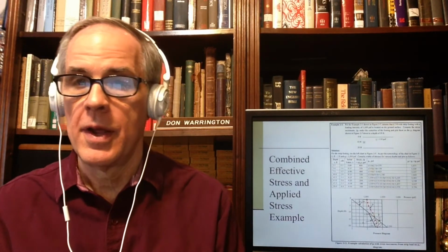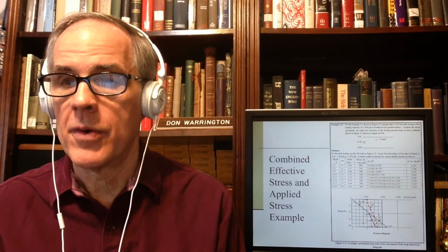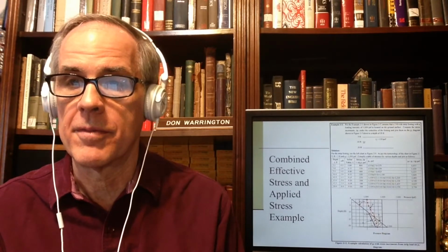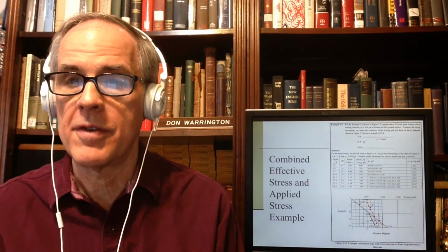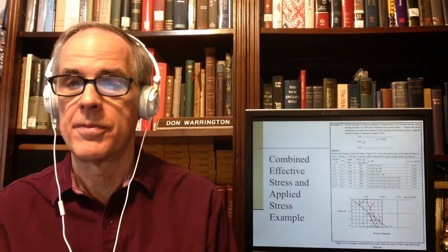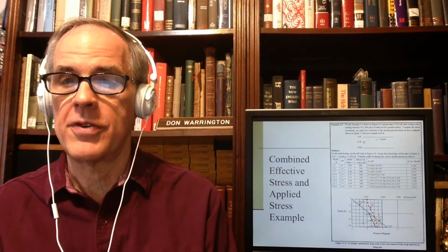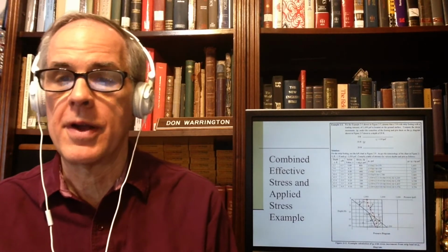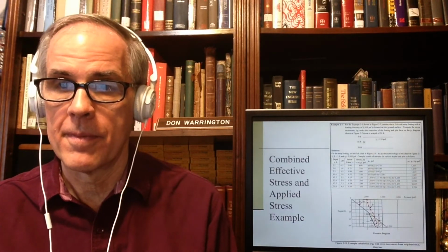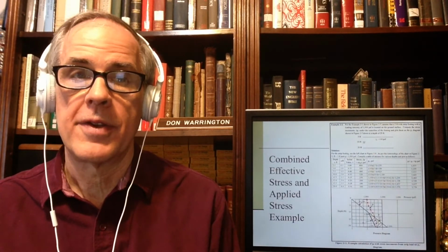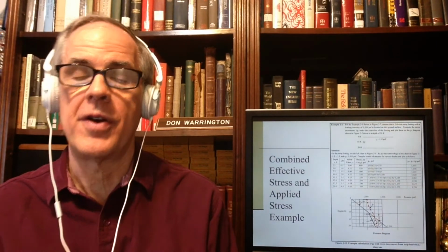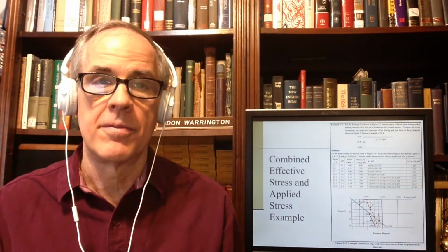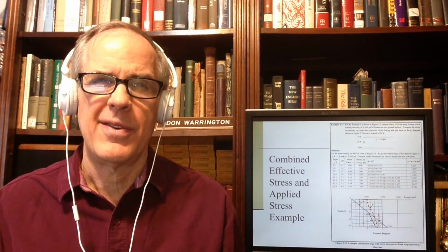Now we're going to put a foundation on, a 5-foot wide strip footing with a loading intensity of 1,000 psf. Compute the stress increments under the center line of the footing and plot them on the P0 diagram. Now, you ask, how in the world do you do this? First of all, we've already been through the effective stresses, so there's no doubt about that. But how did you do these?